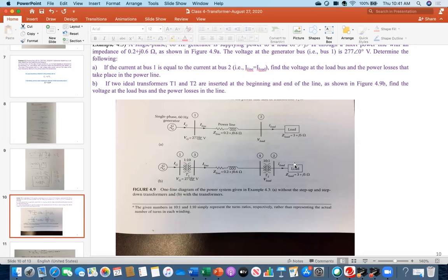But where would you be measuring that voltage from? Like, if you had a voltmeter there, where would it be going? Oh, we are assuming that on the load side, at the other end of the load, it is connected to neutral, so that neutral point is not shown. For example, this point and this point. Because this is a load, for safety purposes the load is connected with the neutral. Those grounding neutral connections are not shown, but I'm answering your question: if you have a voltmeter, one point will be here and the other end will be here. What about for VG?